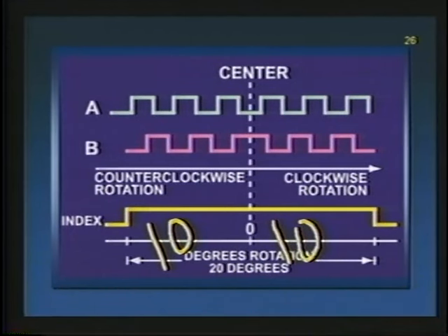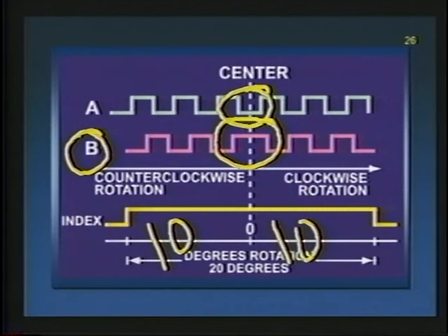Now, we're going to use that along with other signals to help us understand exactly when a system is straight ahead. From there, moving on to B here. Signal B is a square wave, but you can see twice the width there at the exact center point. Another clue for the module, letting it know we're getting really, really close. And signal A should go to the low position. When all 3 of those happen, you are set up. Front wheels are straight ahead.